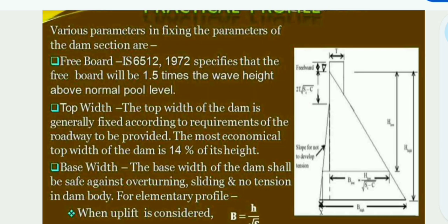Top width. The top width of the dam is generally fixed according to the requirement of the roadway to be provided. The most economical top width of the dam is 14% of its height.